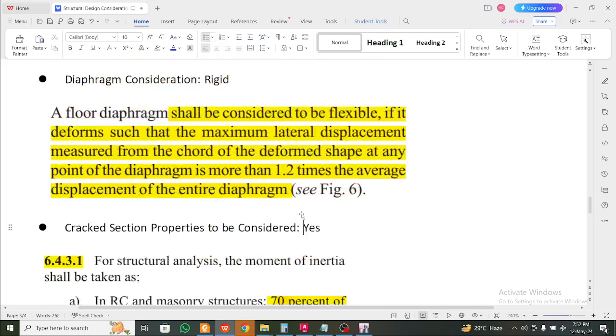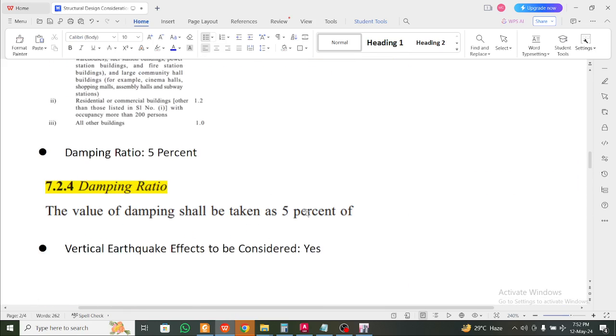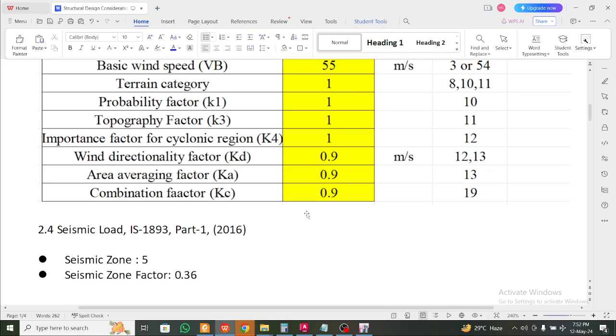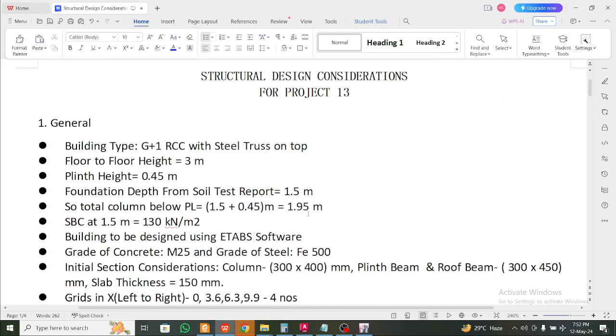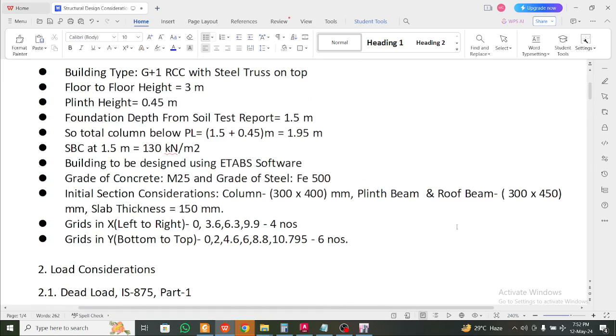So it takes me back to check my design consideration, which I have taken as 300 by 400. If you look at the cross-sectional area, the size of the beam is more, but I'm having second thoughts about whether I can reduce this size. Okay, let's do 400 only.